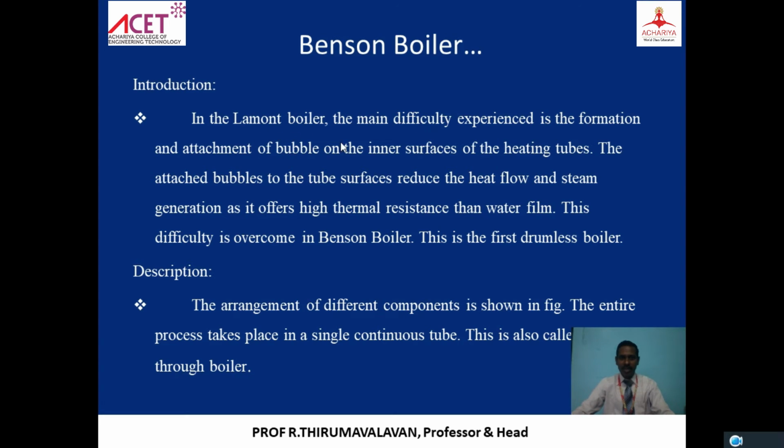In the Lamont boiler, the main difficulty experienced is the formation and attachment of bubbles on the inner surface of the heating tubes. Because of the convection and overheating process, the water vapor separated out forms bubbles in direct contact with the tube.